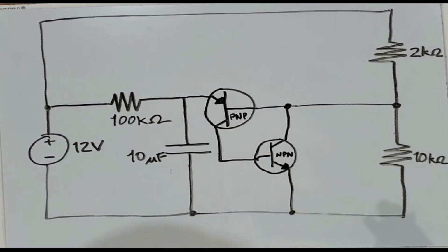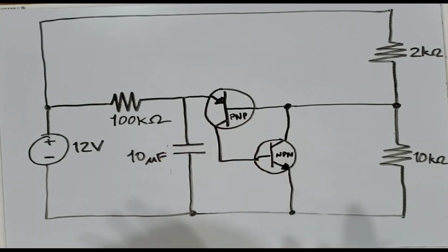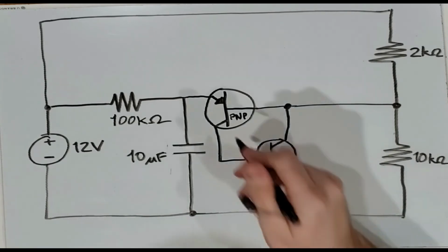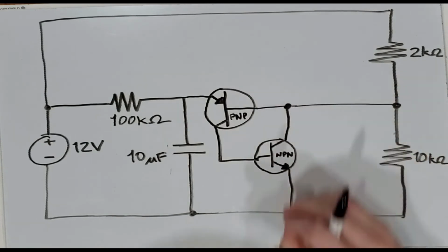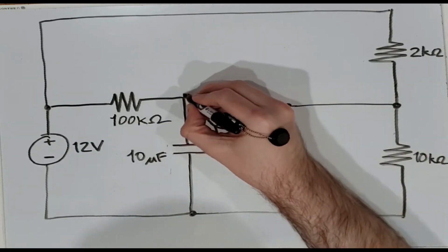The base emitter junction isn't designed to reliably discharge current at all, and it will put considerable strain on the transistor and your power supply. So this isn't an oscillator yet, it's just a fire hazard. We have to provide an alternate path for current to flow while we're discharging the capacitor. So let's add a diode between the NPN collector and the capacitor.